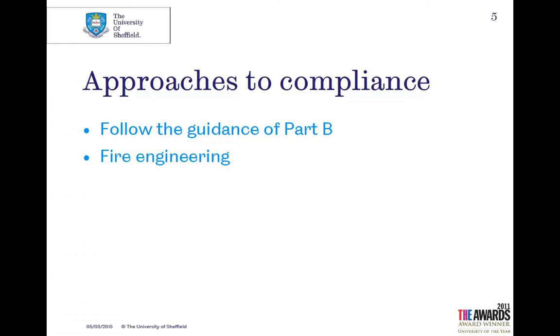Okay? You would normally only be engaged in fire engineering on a fairly large project. Somebody would have to pay this fire engineer for their time, which can be quite costly. So you wouldn't generally be doing it on a small project. The benefit of fire engineering is you can move away from the strict guidance in the document in Part B, and if you're doing much more ambitious projects, big projects, you can demonstrate that your building is safe in terms of fire without sticking to all the distances in the rules.